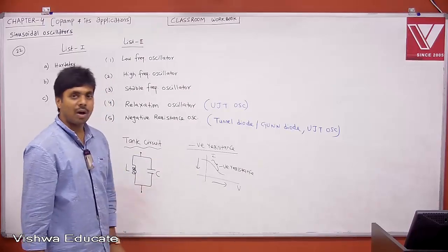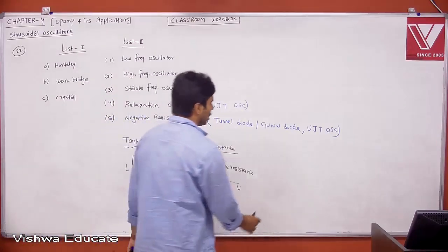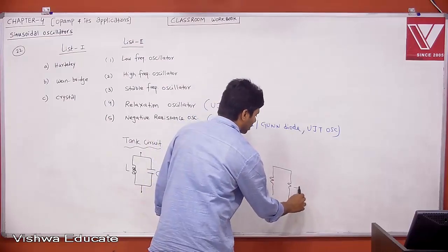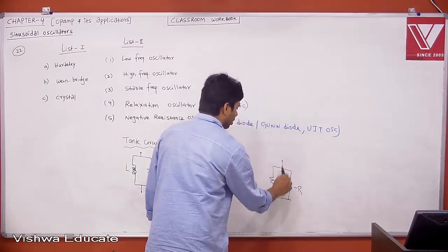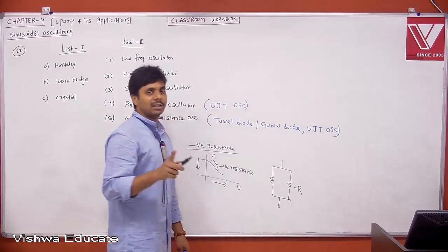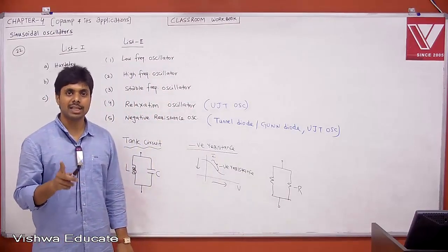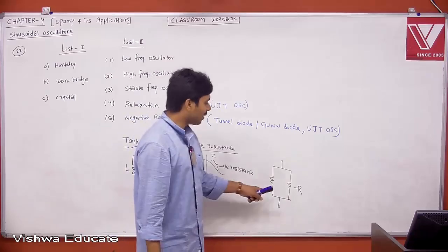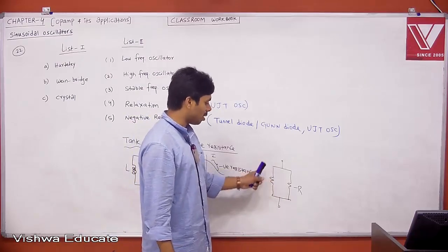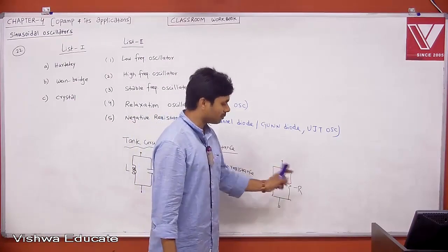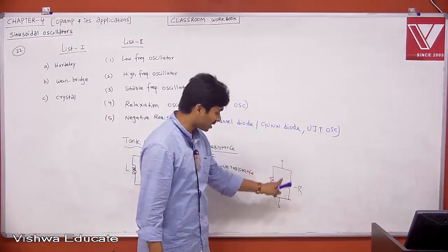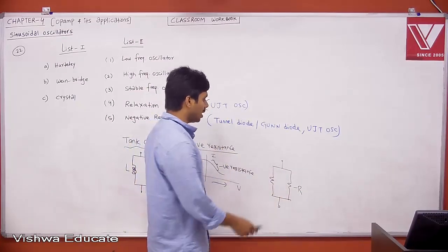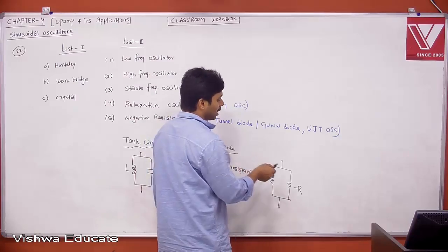Therefore, what will it do? It is like a reciprocal. We have a resistor, and if you have a negative resistor, let us say, can I say both are reciprocal elements? If you can create a reciprocal concept in a circuit, that will give you oscillations. Therefore, if you have a positive impedance or positive resistance, and exactly opposite to it, which is nothing but the reciprocal, the negative resistance region or negative resistance operation, then remember you will get oscillations. Why? If this is what is delivering the energy, it will take the energy.